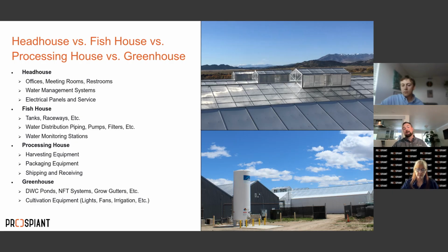However, it's not the best for capturing solids. You have much more surface area at the bottom for the same amount of flow, so a lot of solids settle to the bottom. So when building a raceway type of tank, you have to appropriately stock the tank. The fish are the cleaners. The more fish you have in that raceway, the cleaner it's going to be. If you have a big raceway with hardly any fish, almost all the solids are going to settle to the bottom, and you're going to create a giant biofilm down there, and you're going to get a bunch of chemistry that you don't want in the aquaculture building. Whereas if you do a circular tank, it really doesn't matter how many fish you've got in there. All those solids are getting spiraled down to the very center drain.